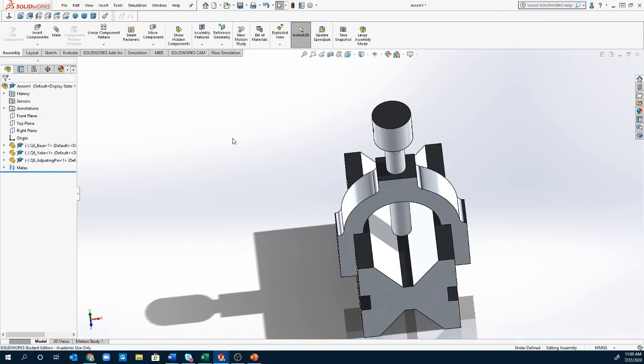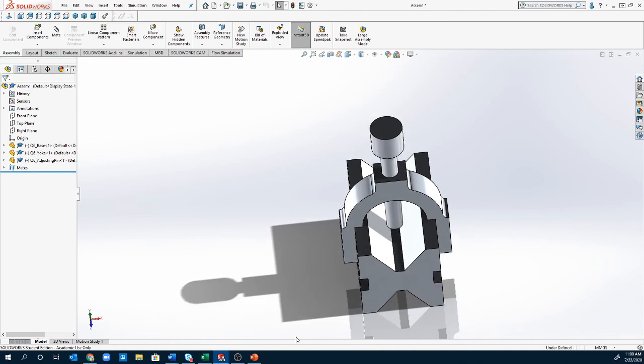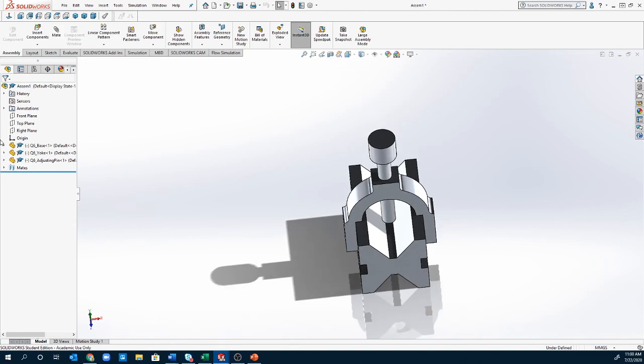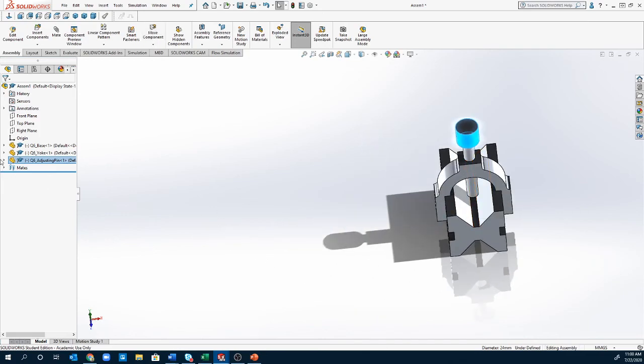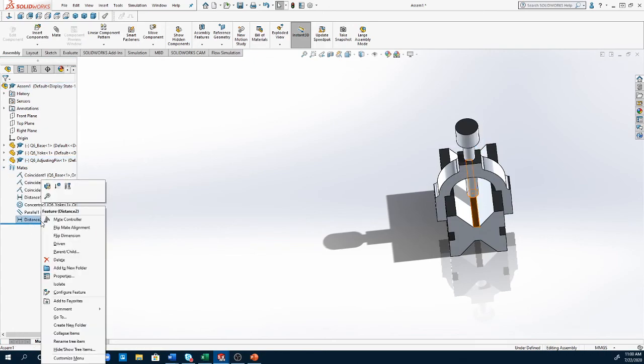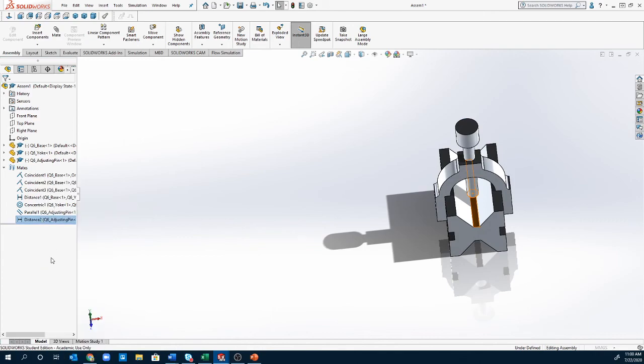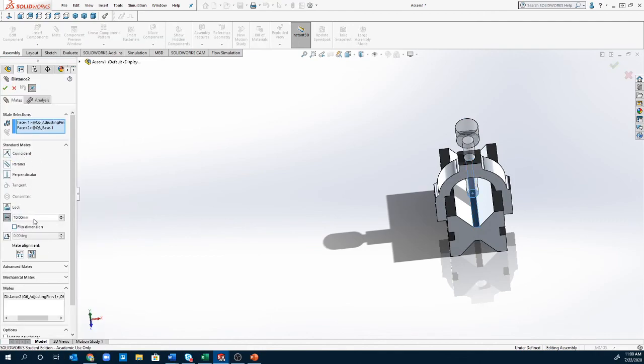Our assembly is complete. Everything should be fully defined, although it looks like a mate was broken. So to figure out what mate was broken, you kind of have to adjust a little bit and sort of feel it out. It's probably this mate here. We can always go back into our mates here, and we can always check and alter what the mate settings are just simply by clicking on the Edit Mate. So let's try this to 20.